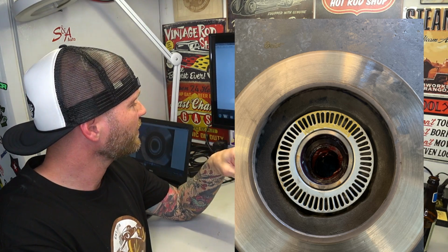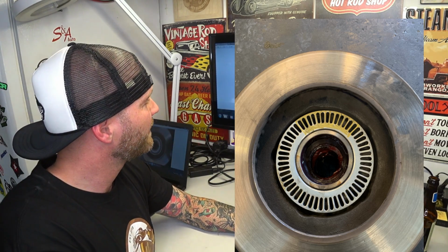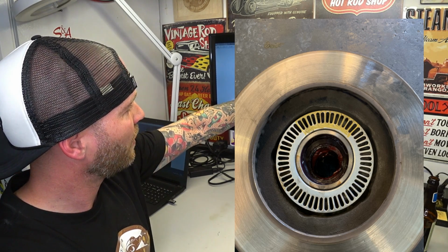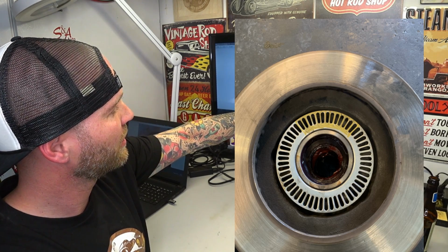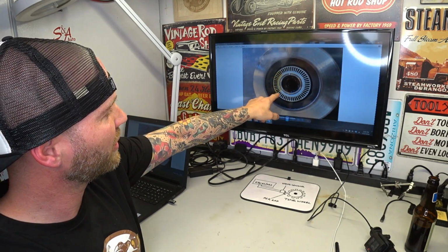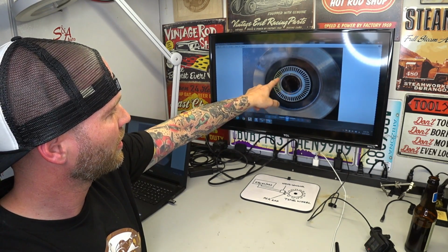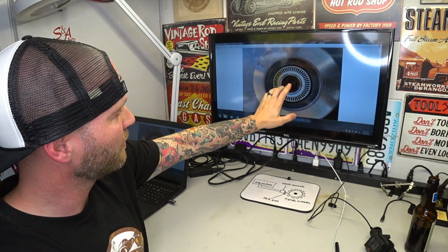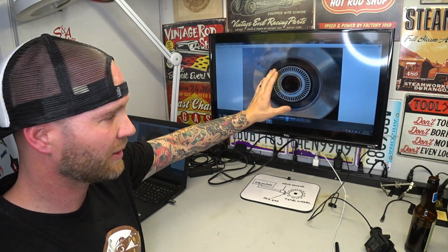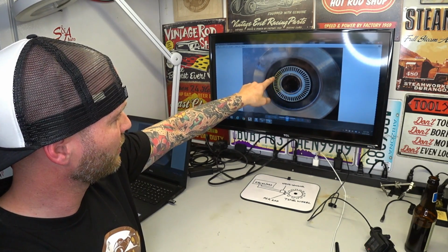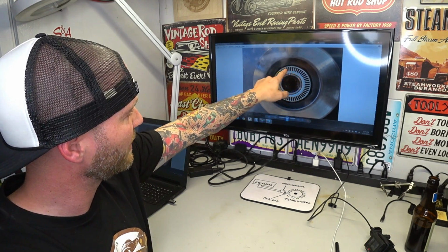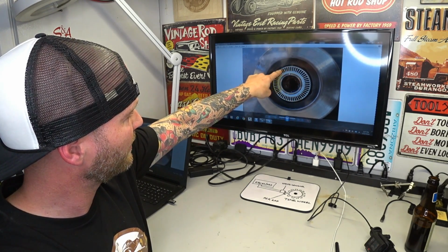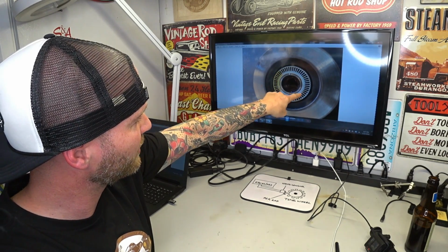Okay, so here is the old rotor. It's real hard to tell from this kind of capture, but all right here is where the rotor's good. This part where I have marked in yellow is lower on the actual rotor assembly. So it's cockeyed, right? This is a low spot, and this is all where it should be. So this is what we're seeing. This is where it's reading good. It gets to here and the amplitude gets smaller. It gets to here, the amplitude gets bigger.